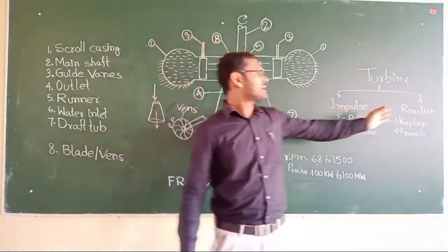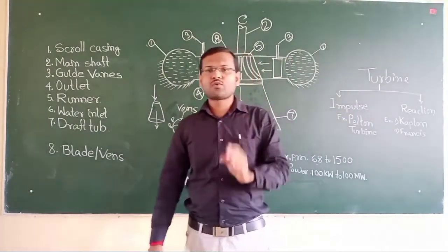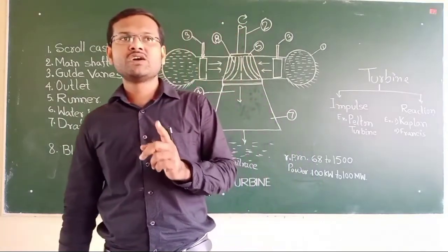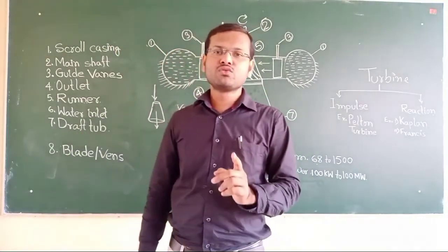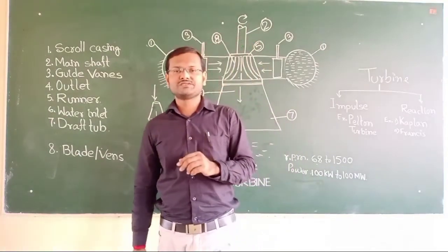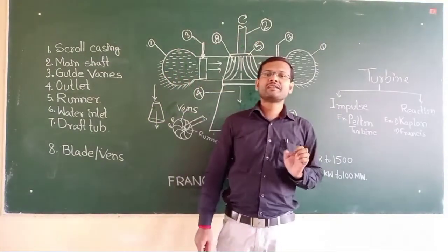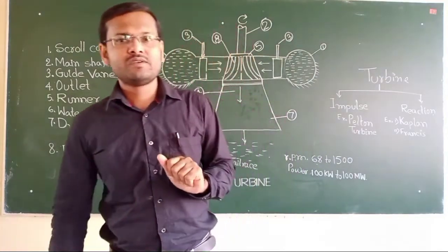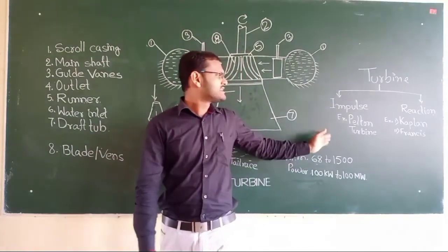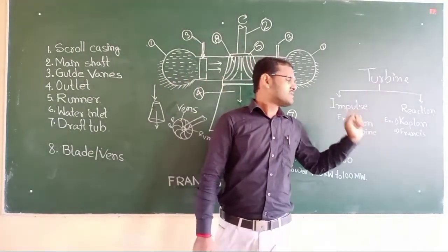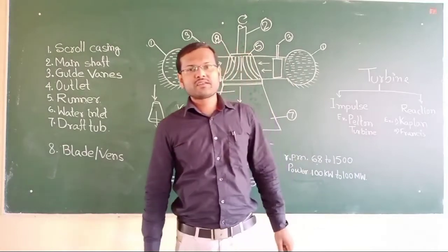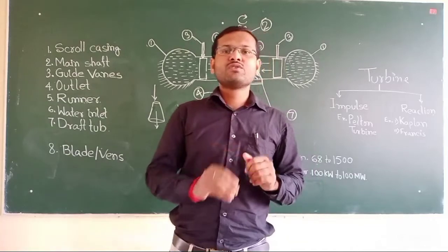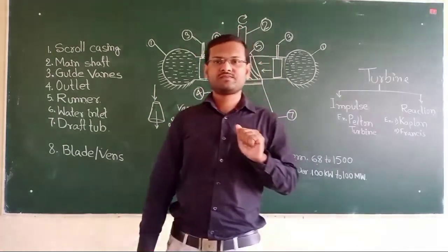and the reaction turbine is the turbine in which the kinetic energy and pressure energy both are converted into mechanical work or mechanical energy. The examples of reaction turbine are Kaplan turbine and Francis turbine. The three turbines, Pelton turbine, Kaplan turbine and Francis turbine, are basically used depending upon the height of head,